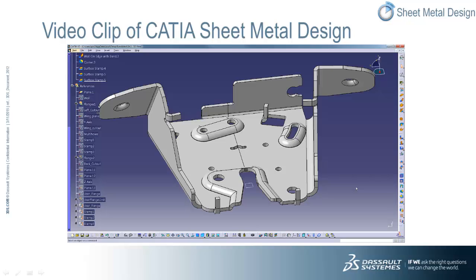It is also very important to know that deformation of the material during the folding and unfolding process is managed through access to company-defined bend tables that include the definition of bend radius, allowance, and sheet thickness, as well as stamping tools tables. This allows the user to verify the design compliance with the company-defined standards and to ensure the design quality. Using the CATIA generative drafting product, designers can also extract documents in DXF format for such downstream applications as nesting and cutting. Finally, it is worth noting that your V5 data is always accessible in V6 and the 3D Experience platform.